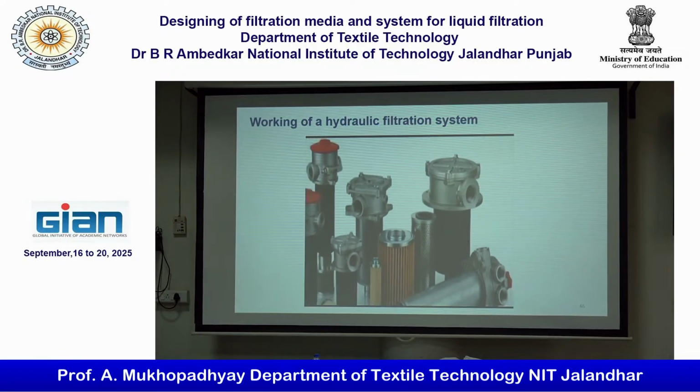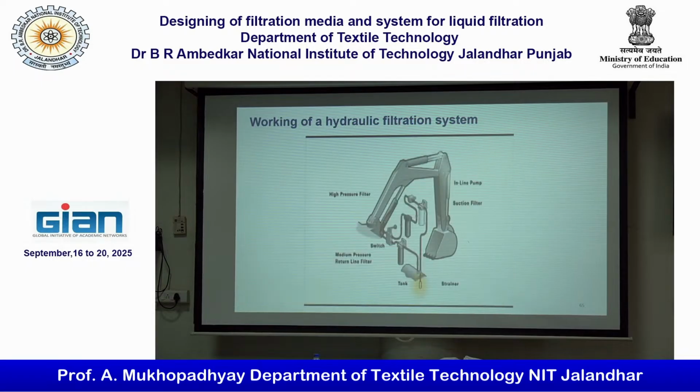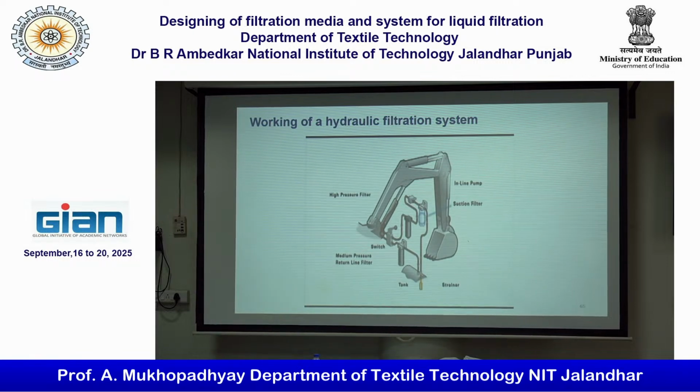Products for hydraulic systems of various applications and sizes. Looking at this animated hydraulic circuit, note how the oil is drawn through a strainer in the tank, which removes larger debris. The oil then goes onward into the low-pressure pump-protecting suction filter.